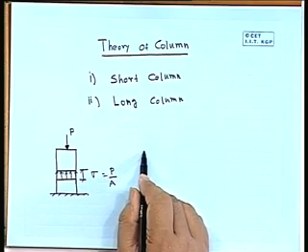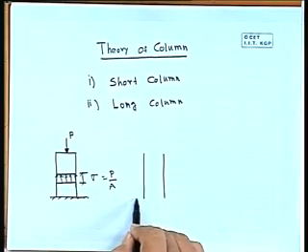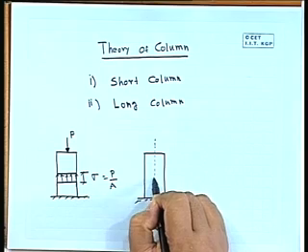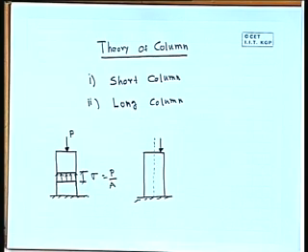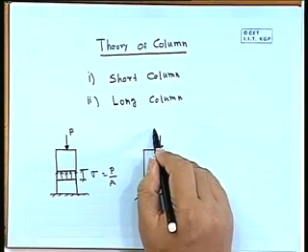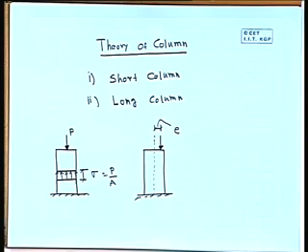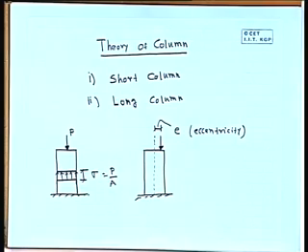Right. Now, if the application of load is different, say same problem if we pick up, say that is the center line. Now, load is acting not at the center, say it is acting a little bit away from the center. So, same P and say the distance from the centroid of the load, if we say it is E. E sometimes we define as eccentricity, right. So, if the load is a little eccentric, not exactly on the centroid of the cross section.